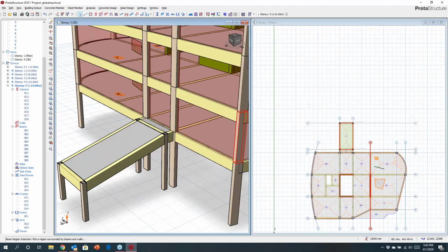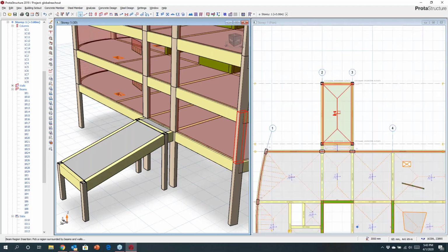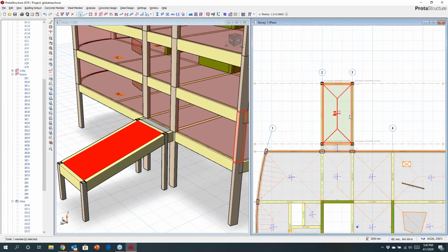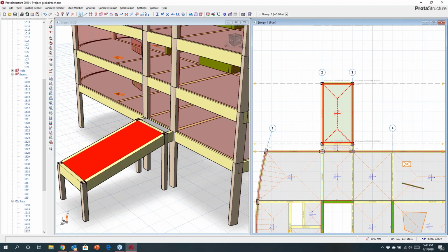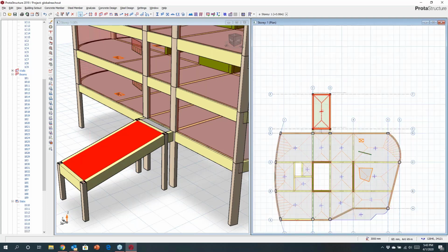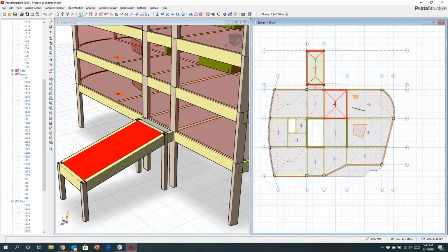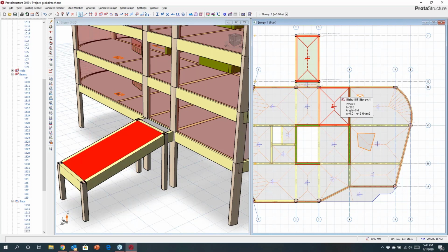Okay. Now, at the same time, because I've set the plane up, I may want to go back to the slab properties, and I'm going to choose that the slab doesn't contribute to the rigid diaphragm, so that this would probably be properly considered within the analysis. You can't have sloping and rigid diaphragms meeting. So that gives you an idea about how we go about creating the model.